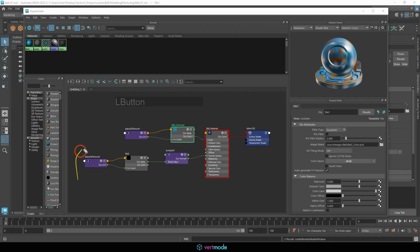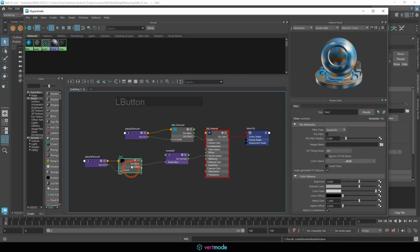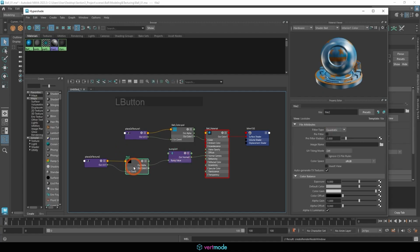Likewise, you can see this bump set up here. And this is the bump that is driving our bump texture. This is what we landed on when we created it, the bump 2D. And we'll talk a bit more about that in a moment. But this is the file we need to access that's linked into this bump 2D. So to access the file, we can click on it here, and it's the exact same file node as with the color. So you already know how to use it.